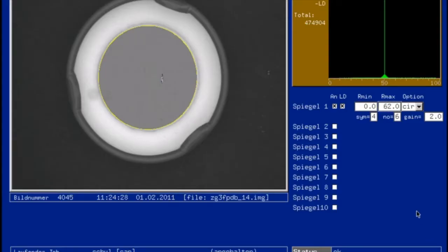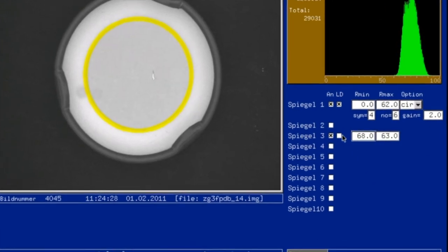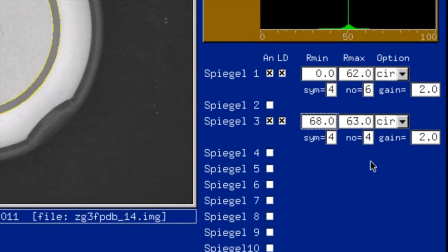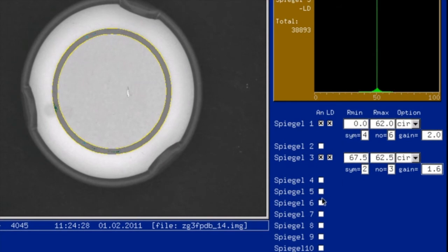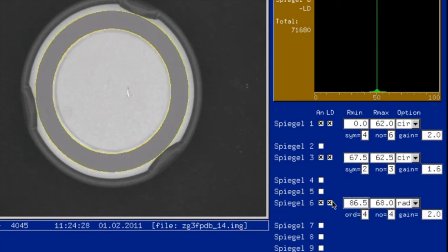To get the best results for the evaluation, the object must be separated in several surfaces. The transition will be checked separately through another circular scan. The sensitivity can be pulled down in this area. The compound area, also called dip, can be verified circular and radial. For asserting underlaps, you should choose radial. The area can be checked additionally to find gray tones and to recognize possible underlaps.